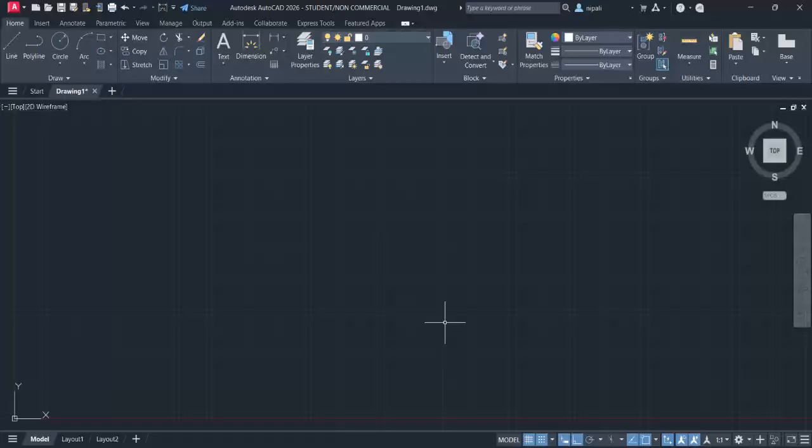YouTube tutorial. So for today's class we shall be looking at the status bar, which is this bar that appears at the lower edge of the window. Also, you can just click on here to access more functions of the status bar. With that, we can say that the status bar appears at the lower right corner of the program window. It contains an assortment of tools for controlling various drawing aids such as grid display, snap mode, and polar tracking.